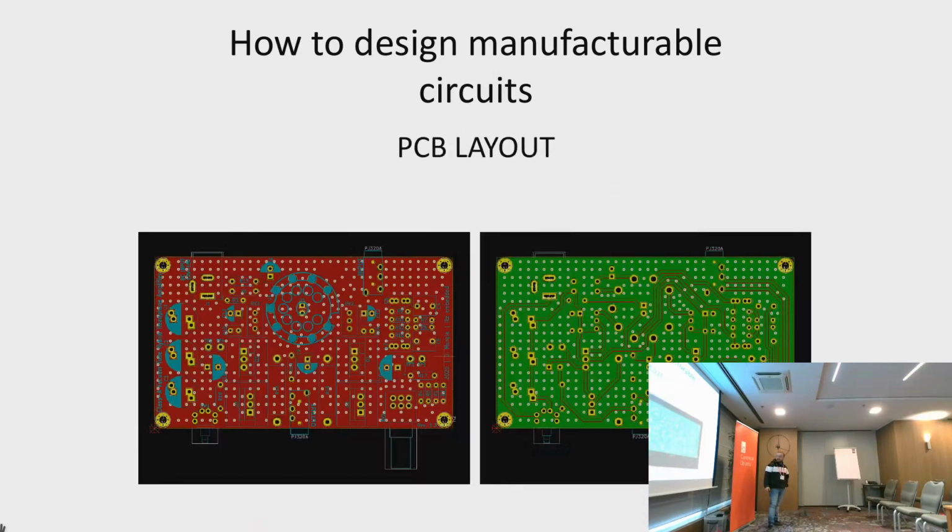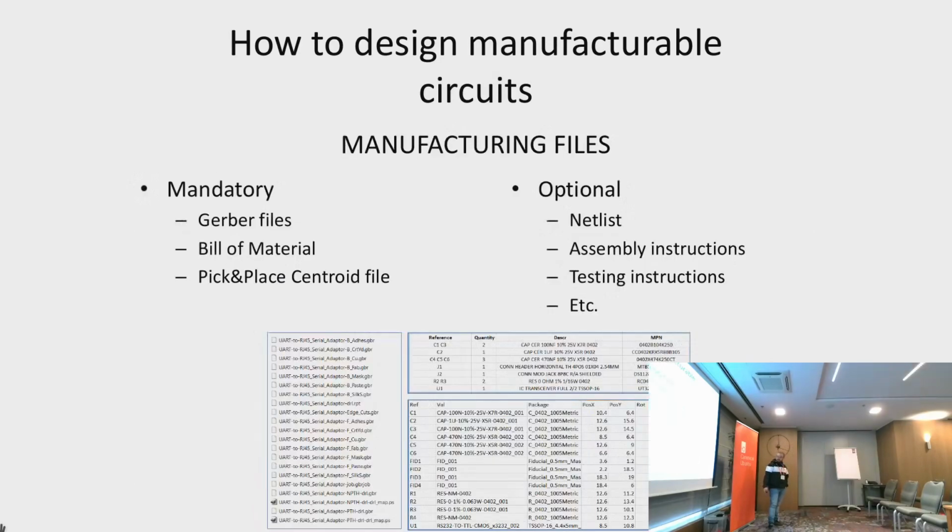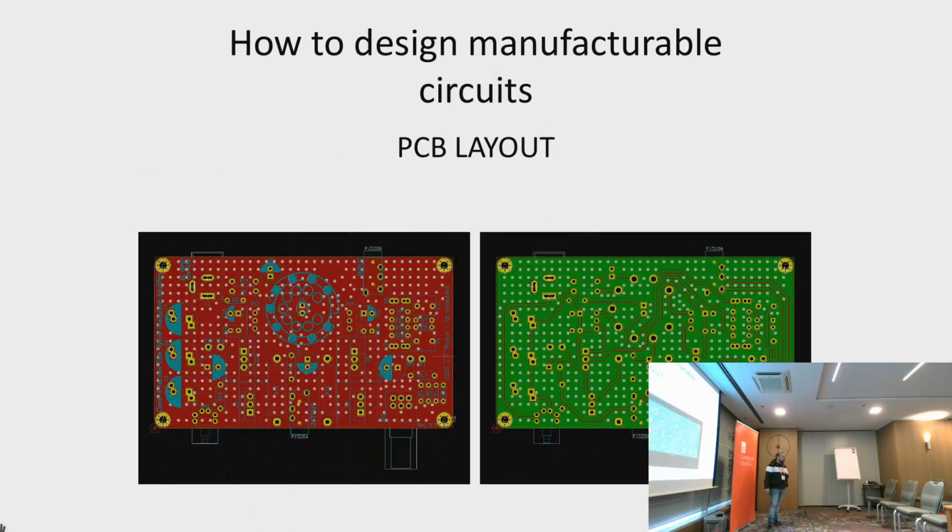Yeah, different project. And then for the layouting part, can you set constraints for auto layouting? Like in your analog example, you might want parallel lines for the inputs, or very short lines. Personally I don't like auto routing. I prefer to do routing on my own. But the CAD tool can help you if you have a differential line, for example, to route two tracks with the same length. But then you need to set up the proper constraints upfront, so the distance between tracks and how thick the tracks must be for proper impedance. So that's definitely possible within the tool.